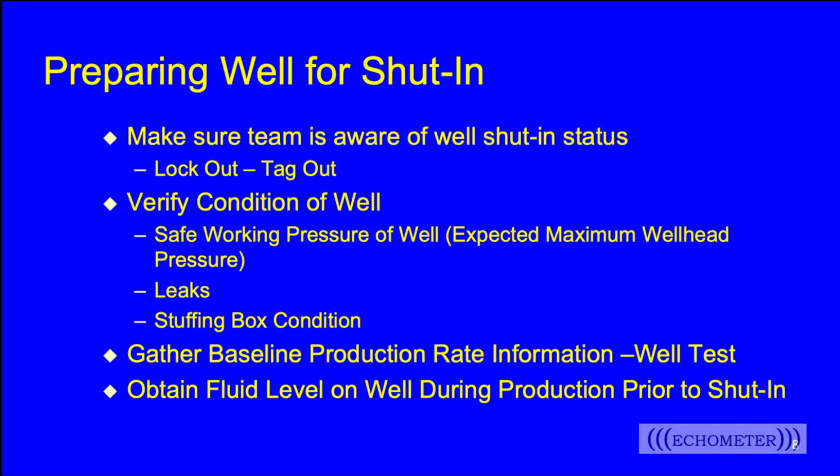We'd also like to have a producing fluid level on the well prior to the shut-in. And Gustavo will work through an example. He'll show you how this is used. But again, that producing fluid level is used to determine the fluid distribution in the wellbore after the shut-in. We assume that all the liquid above the pump in the producing state is oil. And then that's the starting point for the afterflow that gives us the fluid distribution after the well is shut in.